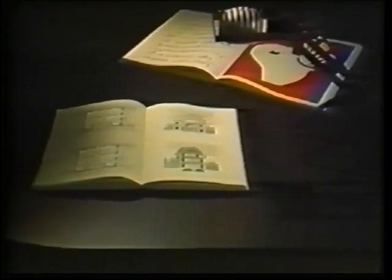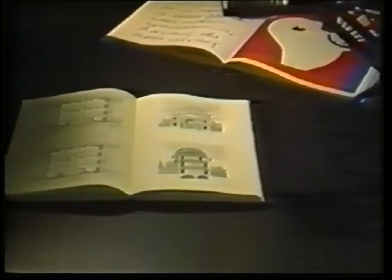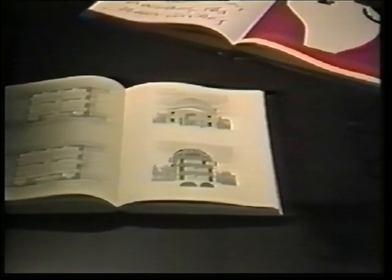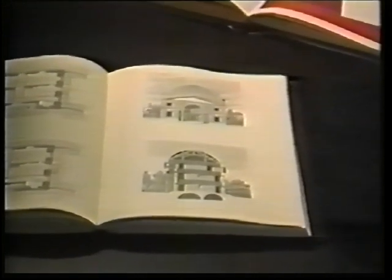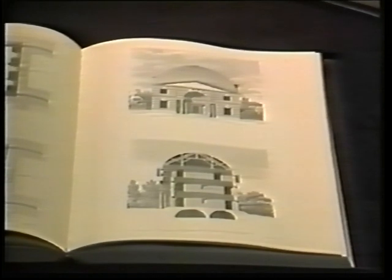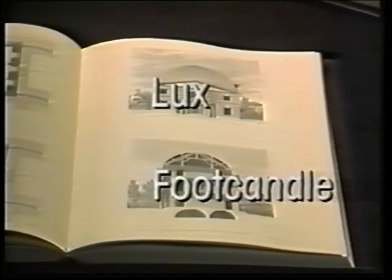Now let's use that light to look at these books. Are there 1,750 lumens of light falling on this page? No, because lumen is only a measure of light at the source. The amount of light that's actually falling on this page, in fact, the intensity of light illuminating any particular area, is measured in lux or in foot candles. 10 lux are approximately equal to 1 foot candle.